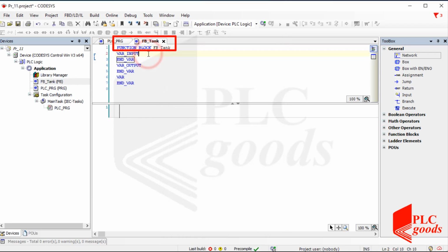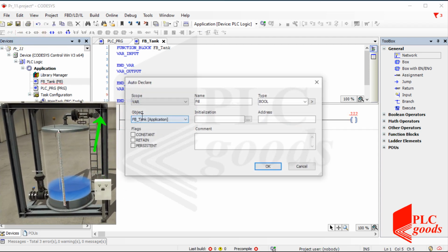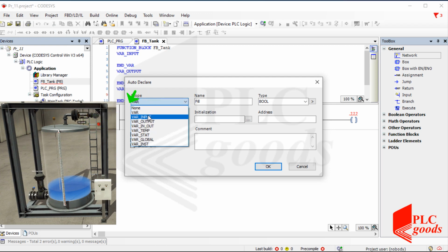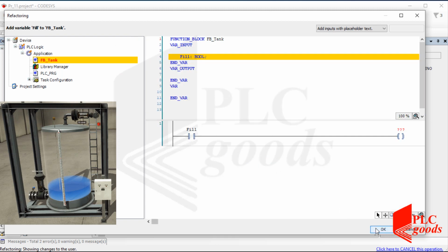Well, function blocks usually have some inputs, outputs, and also some local variables. The main difference between functions and function blocks is that, functions don't store any variable for the next execution, but function blocks use a part of the PLC memory to store their local variables. Let's continue. Well, I want to use the green push buttons to open filling valves. My function block receives the state of push buttons as its input, and then determine the state of filling valves as its output.